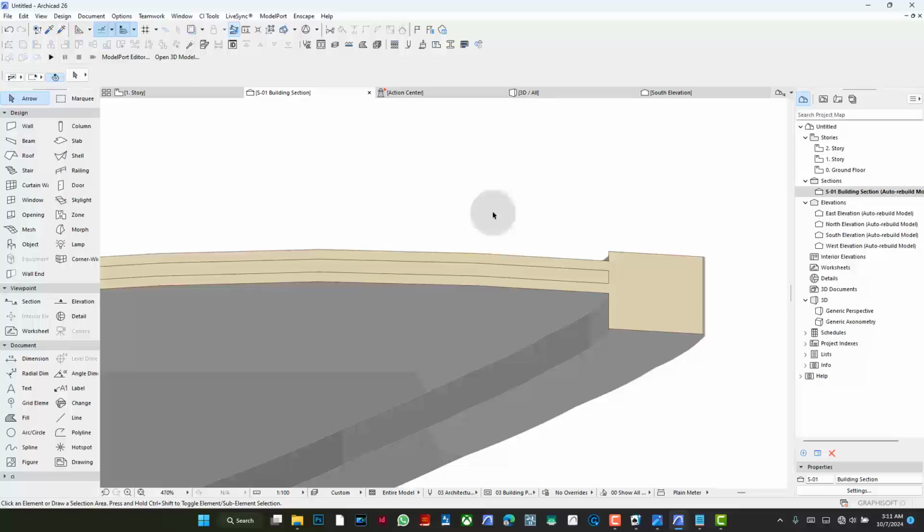For my Archicad version 26, I have complained to Graphisoft already, but I guess they're not paying much attention to 26 anymore. Each time I'm editing a shell, if I open the shell tool dialog, that's like double click on this or bring it up on the other side, Archicad crashes. If you run into that problem, just restart Archicad and pick up where you left off. What I'm doing is trying to do everything I can to not open that dialog. Alright, that said, let's get back.